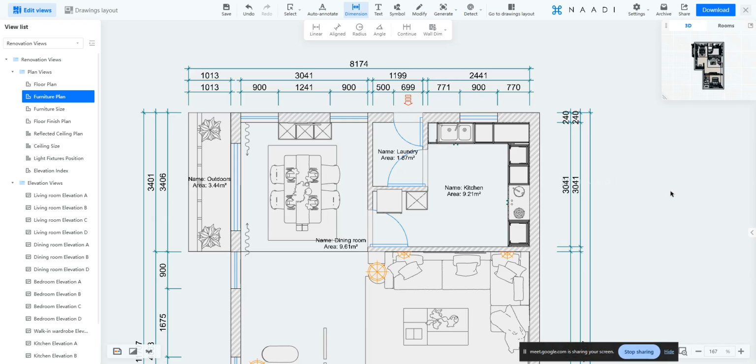Some organizations don't mention the width, they mention the shutter dimensions of the double door cabinet altogether. If it is 900, they mention 900 as a shutter dimension there. Obviously the shutter dimension will be 1 mm lower on both sides, and you have your shutter gap at the center as well, right? So it will be 2 mm lower than your actual cabinet width. So they have a practice of mentioning that shutter dimension. Some organizations want the shutter dimensions individually, which means if it is a 900 mm cabinet, they want the first shutter to be 450 and another shutter to be 450. So can you see, a single dimension requirement for the same double door cabinet, but different organizations follow different standards, right?